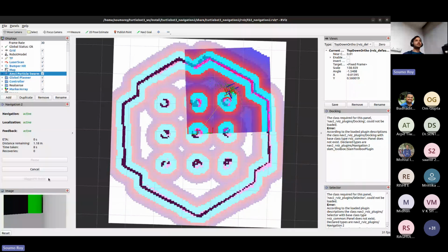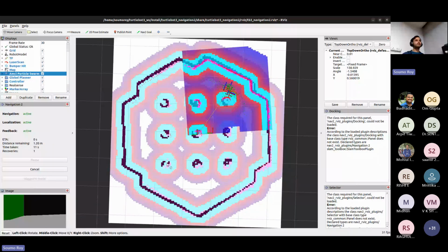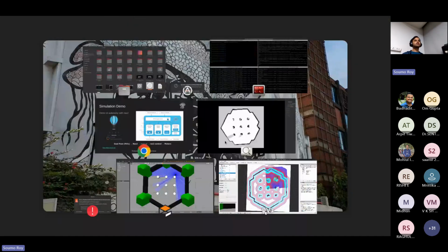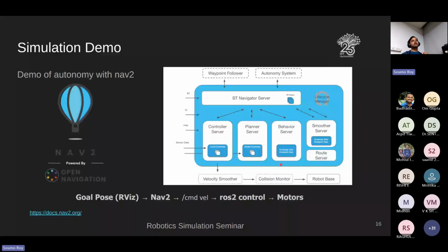So this is the condition where I've given an infeasible path and now the robot is stuck. This is where recovery behavior comes in: if you know that there's a wrong path or a wrong scenario plan, you need to model a behavior so that it can go back to where it originally was, and because of which we calculate something called a footprint of a robot so that we can analyze its behavior.